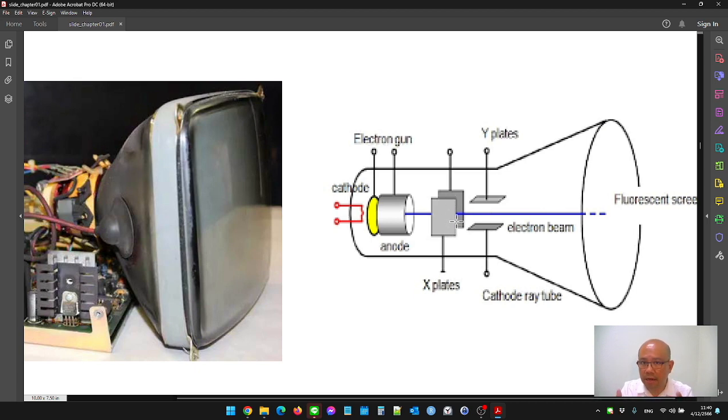The coils generate a magnetic effect on the electrons. The electrons move along the x and y axes, scanning from the top left to the bottom right. By scanning very fast, it generates brightness, and inside there are mechanisms to turn the electron beam on and off during scanning, which generates the picture by the scanning technique.